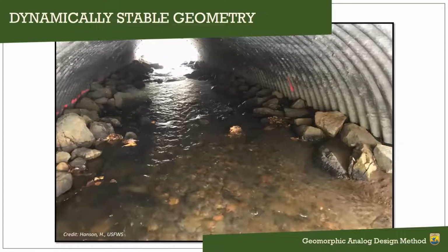that went through the 2012 year flood. The bank materials made it through that. In fact, we're even seeing some deposition on the banks, which we'll talk a little bit more about later. But Matt mentioned yesterday that once the flows leave that bankfull channel, we should be seeing deposition on our banks. However, inside of a culvert, we are still constricting those flows. So we do need to use large stable material for our banks in the culvert.